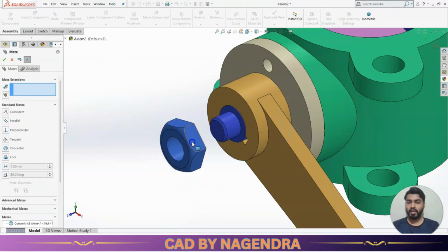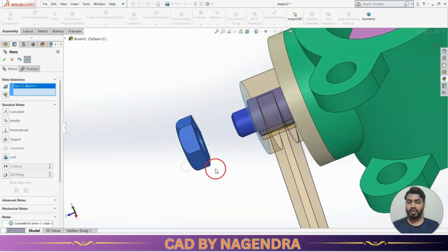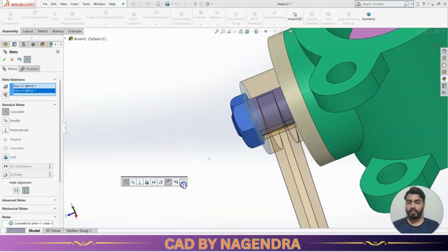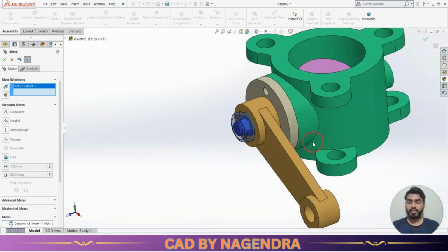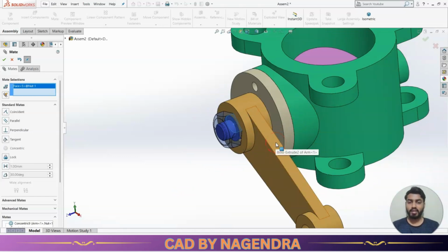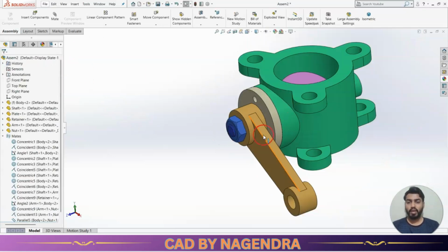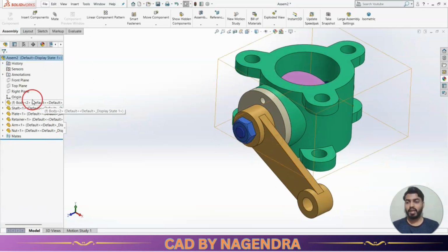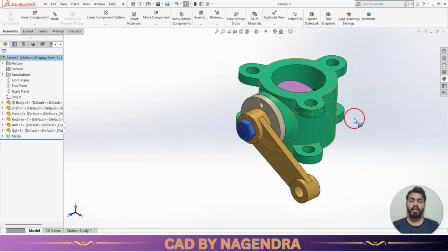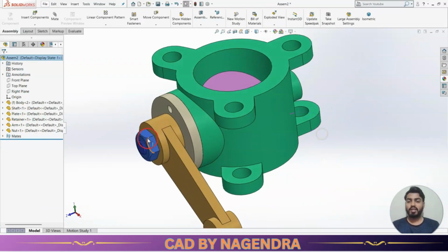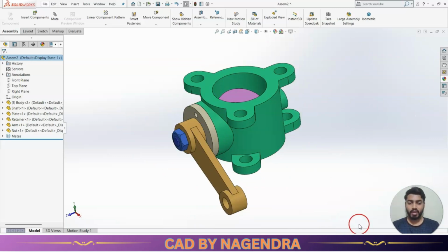Okay. Then this face should attach with this face. This face with reference to this I'll select, or else on top also we can select to make it a parallel relation. So we'll try one way of applying mates. If we are getting any error, we need to try to change that selection of faces. So again we got fully defined here. No error is showing.